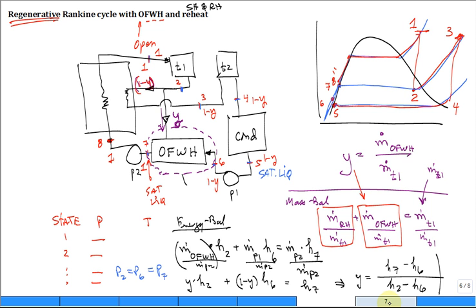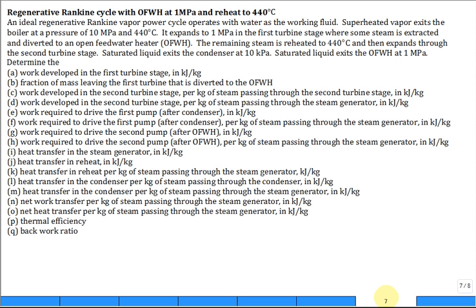All right. Well, once I know that I want saturated liquid here, and I know the pressure at state 2, and we know the enthalpy because we expanded isentropically from 1 down, then we can calculate a lot of other parameters. Let me show you some data. These problems are long, but you just go slowly working through the cycle as I tried to show you for the mass flow rates and the pressures.